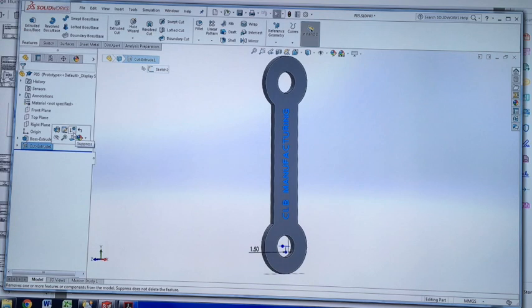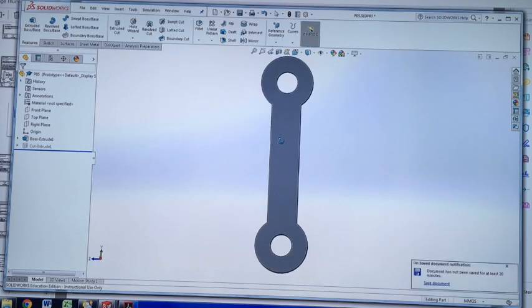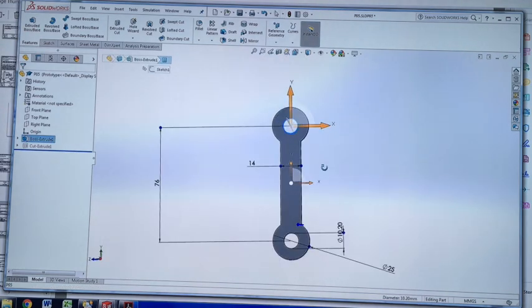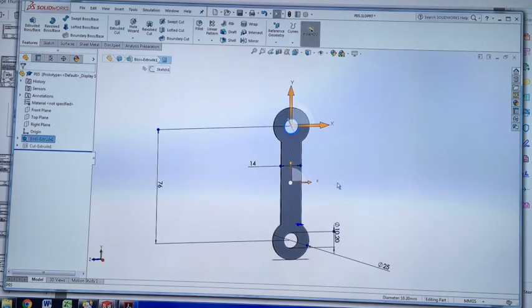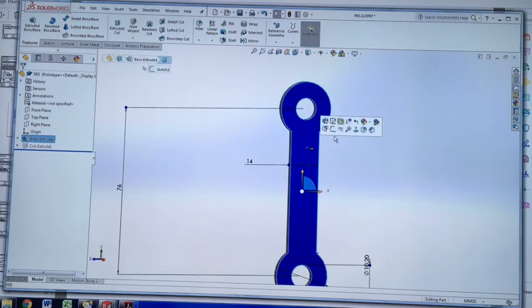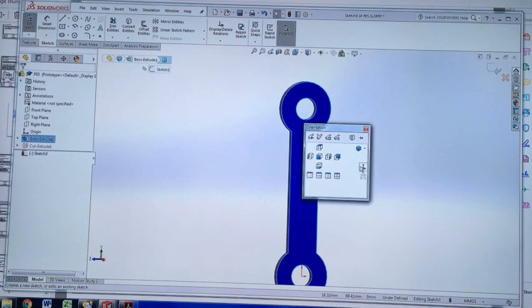Let's just assume that you want to change it to something else. So we're going to suppress that. Now with this part, again, we need to keep those holes, A to B. They need to be in the same position, but the main shape of this body can change. So this is one where we can actually add some material back on.